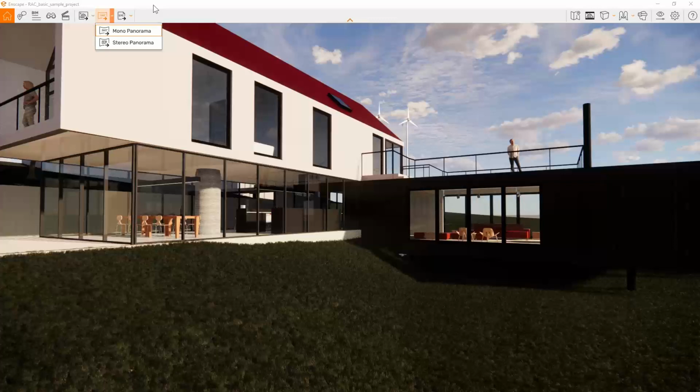These are essentially where I can take my whole Enscape project and bundle all that up. I can navigate around, I can change the time of day, I can go to certain view setups, and I can pass that off to a client, a customer, and then they can navigate around just like we're doing. The only thing they're going to lose is the ability to have that live link to Revit. So whatever I'm changing in Revit, whether it's materials or editing the model, it's going to update in Enscape. They're just going to lose that ability because the link is essentially severed. It's not going to be there.